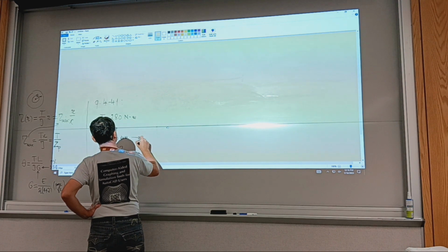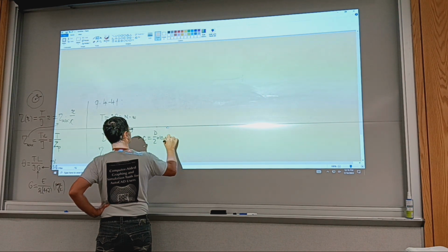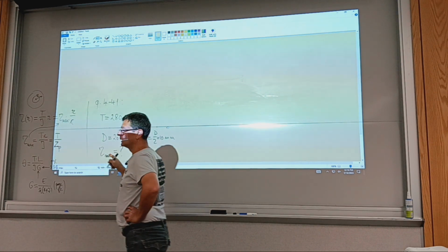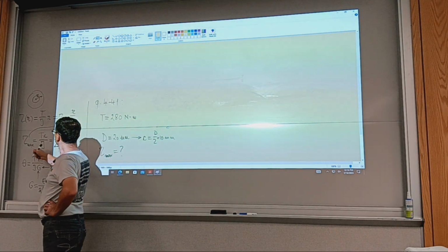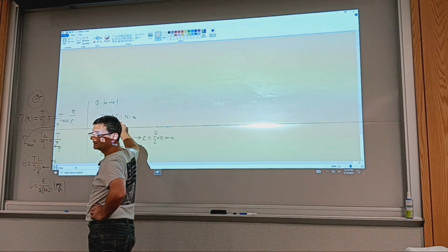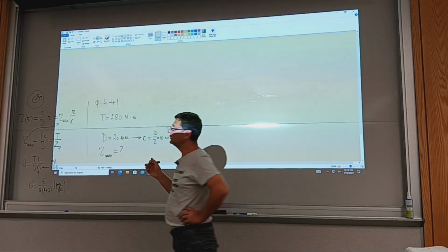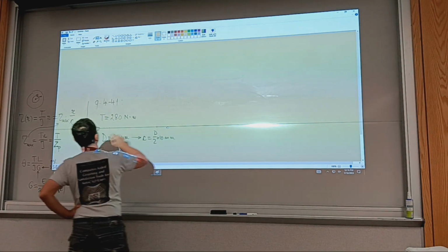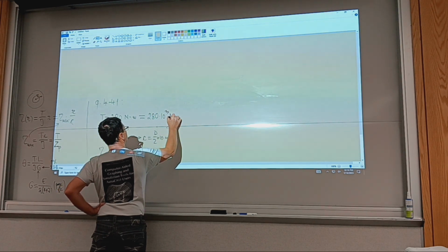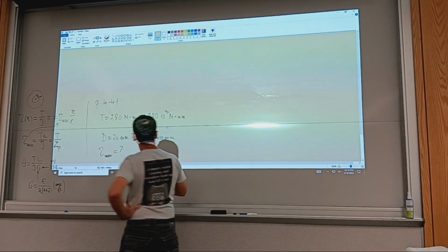Yeah, so you said radius C is going to be D over 2, 10 millimeters. When applying this equation using millimeter to the power 4 or millimeter to the power 3, the torque should be in Newton millimeters, remember? Because if you use all millimeters and newtons, you get megapascal. So we'll get tau in megapascal. So this will actually be used as 280 times 10 to the power 3 Newton millimeters. This is the value that we'll be using in the formula.